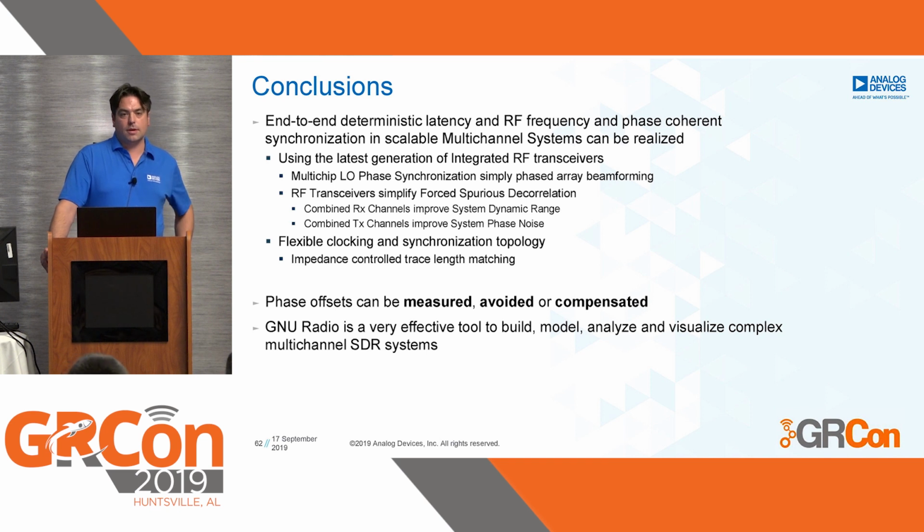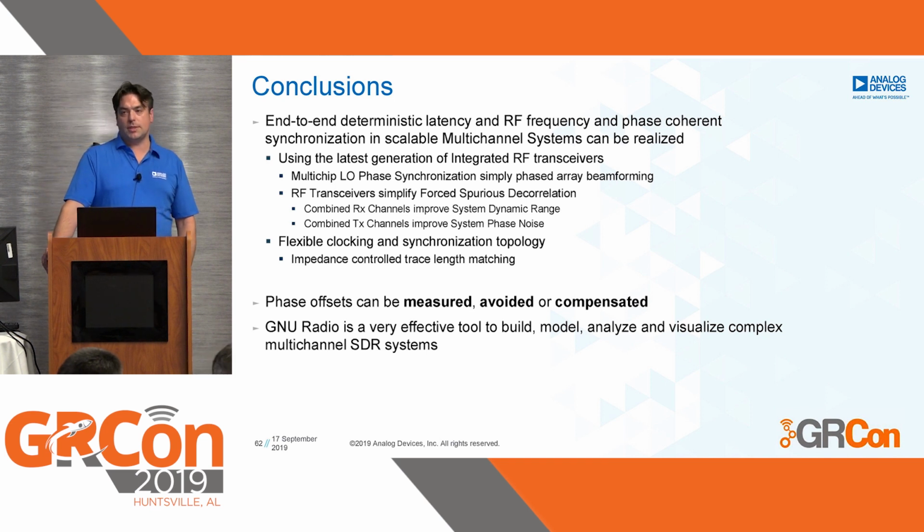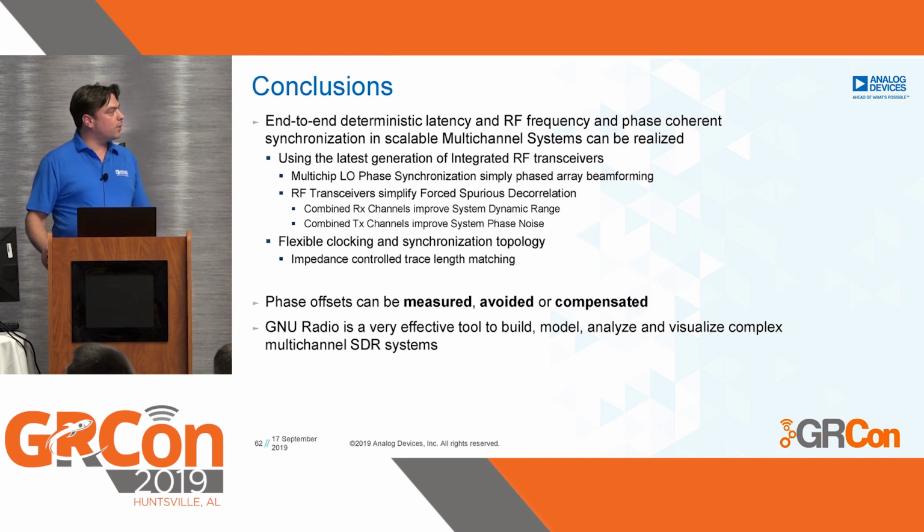It always requires a very flexible clocking and synchronization topology, and of course all your traces, everything, need to be impedance and length matched in order to actually synchronize those things. The phase offsets can be measured, they can be avoided, or most of the time they're just compensated. And last but not least, GNU Radio is a very effective tool to build, model, analyze, and visualize multi-channel software-defined radio systems.